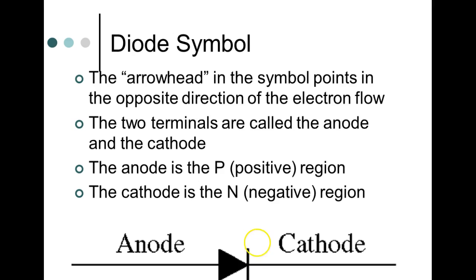And then of course everybody okay on the symbol? To forward bias it, we point the cathode toward the negative and the anode toward the positive. If you see on a test that the cathode has to be negative and the anode has to be positive, and you mark that true, you're going to miss it. Because very seldom are you going to, normally you measure the same potential on both sides. You either measure 0 on one side and a positive potential on the other, 0 on one side and a negative potential, or positive on both sides or negative on both sides.